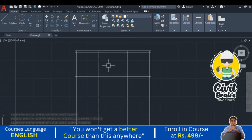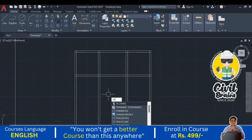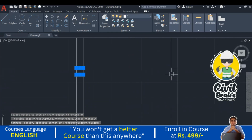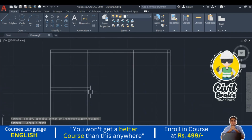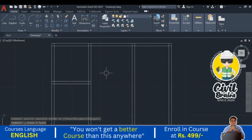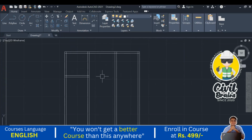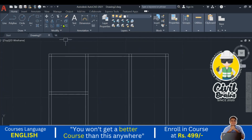For not getting confused, I just trim this wall first. Let's go to the trim command, or just type the shortcut of the trim command is TR. Trim command, press enter, delete this one, delete this one. Okay, and this also, you just delete that one. So we will not get confused here, because this is our first plan, right? So that's why I'm deleting this one. From the next class onwards, you can draw that one easily, once you get familiar with this. Okay, so this is how much. Okay, I just trim these corners so that you can easily get an idea.